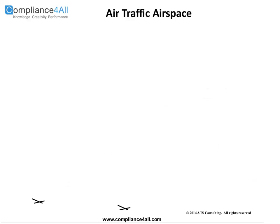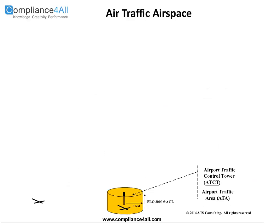Okay, so in this case, here you have two airports that are out there in the beginning, and all they are is strips of concrete or whatever, even grass or land. But they're out there, and as traffic builds, someone says, well, this is going to be too busy. We need to put in some kind of a safety thing here to create some order. So at that point, you put in a tower cabin, which is there to provide that order around the local airport area. And as soon as you put one in, by statute, there is airspace assigned to that. It's below 2,000 feet above the ground and a 5-mile radius of the airport. That's called the airport traffic area, and that's what the tower kind of owns.